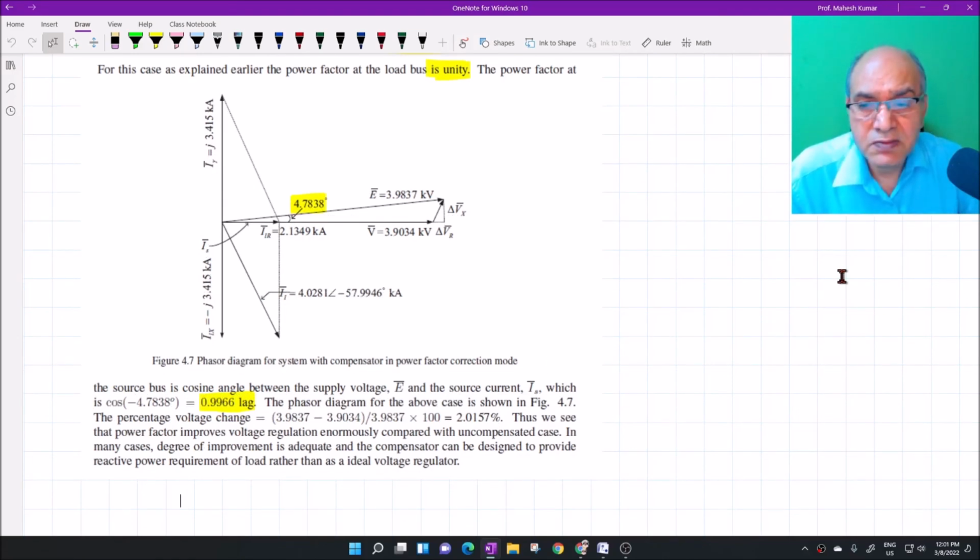In the next class, we will learn how to compensate three-phase unbalanced system. First, we will consider three-phase three-wire system, and we will see that an unbalanced system can be perfectly compensated with the help of purely reactive network to achieve unity power factor at the source.